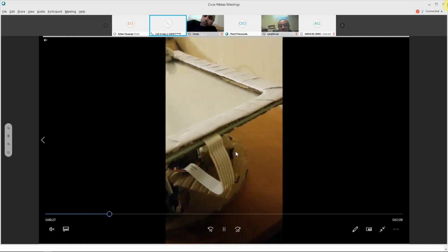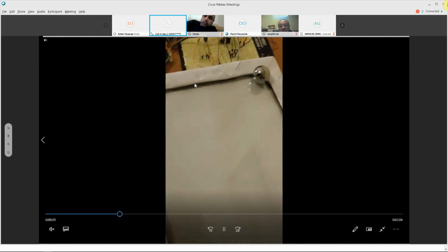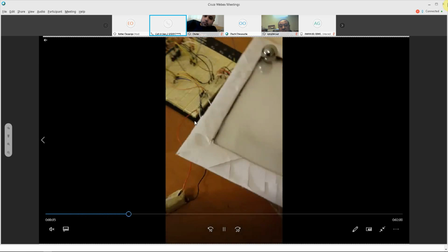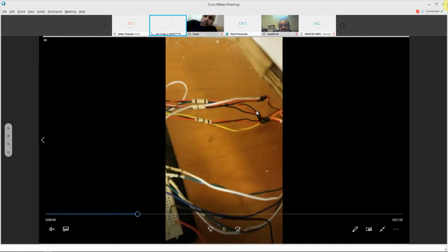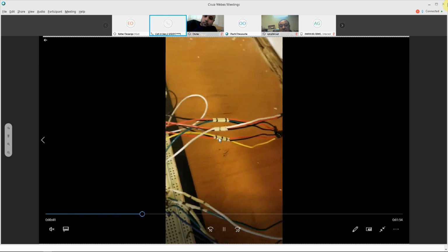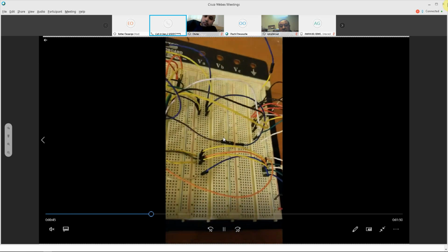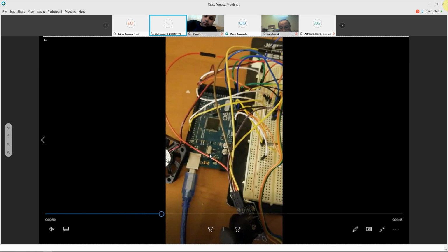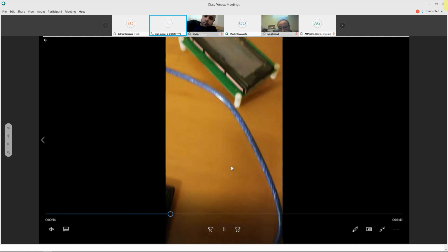This is more so the prototype of this project. It's made out of cardboard, but it's pretty decent. It really depends on the servo arms and their interaction with the servo. So it's the interaction between the servo arm and the supporting rods. So probably what could change for the joints is a clevis so that it can make it more sturdy or more strong.